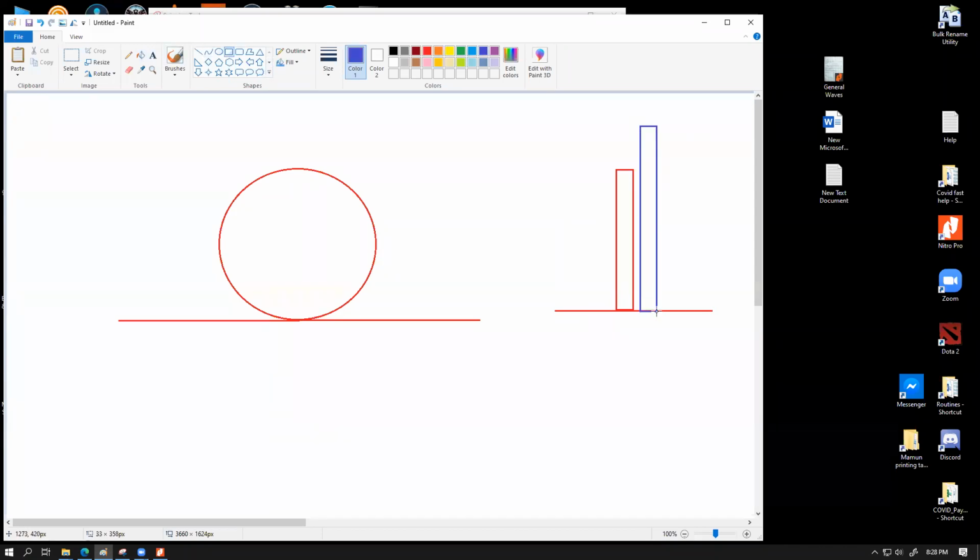A meter rule can be placed beside this thing over here, and that should be accompanied with another set square, to make sure that this thing is perfectly vertical. The reason I'm using a meter rule and set square as well is because a set square might not have as big of a side as the diameter of this thing. So having a meter rule can help to make sure that the whole thing is perfectly vertical. And this thing should be checked in multiple different places.